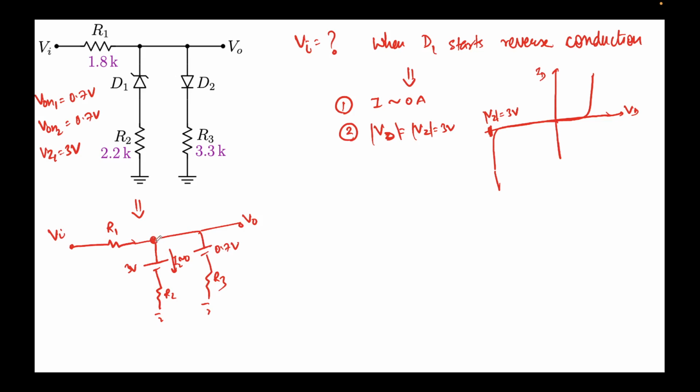This means this voltage over here, V0, since I2 is approximately equal to 0, V out will be equal to 3 volts, because it's 0 here, and so that potential would be 3 volts. So if V0 is 3 volts, there is some current that will be going through here, that is I3. So this is our step 1.